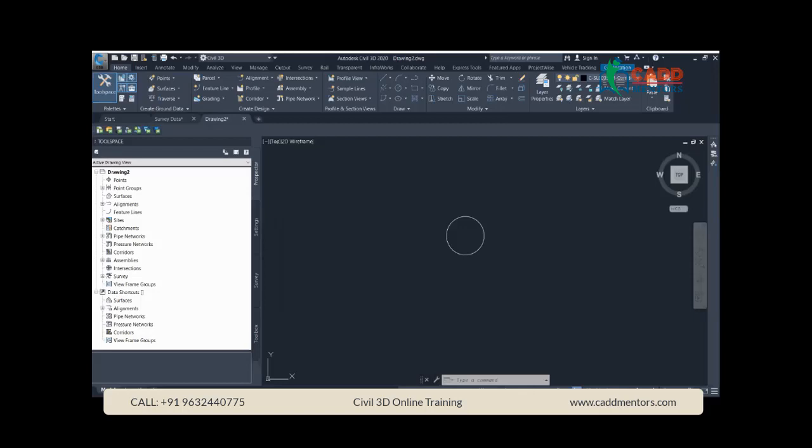And Publish, you can do it as a 3D solid. Sometimes you have so many external references, and you can't share every file with others, so you can use eTransmit as a publish option, and that is what it is for. And Print, we know, is just to make a PDF if we want to see how the drawing looks.